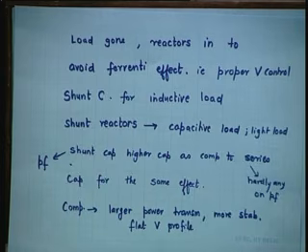You must have studied in the stability chapter in your undergraduate: what happens when suddenly the load is off? Because the generation is still there, and you take time to reduce generation. It is not a joke, it is not just switching on and off. You have to reduce the amount of steam, the valve has to be closed, or the water gate opening has to be closed.